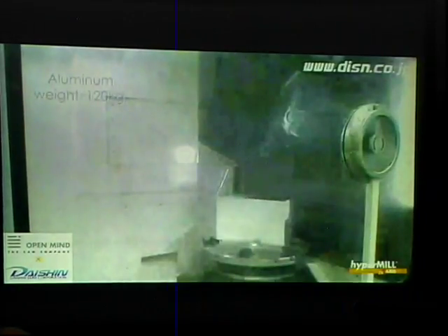Question B. What prevents bugs in the translation between the 3D object and moving the head into a wall and destroying it? What's the certification process you go through to run an $80,000 or $200,000 machine so you don't destroy the head with bad G-code? There's a couple of ways. There's secondary products that do check for that. A lot of the CAM programs nowadays have routines built in where I can define the scope and the space of my machine, where the cutting bit is, where there's supporting material, and where there's electronics, and it will make sure it avoids those areas.